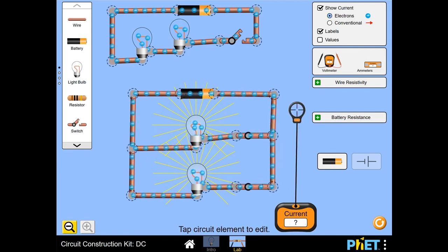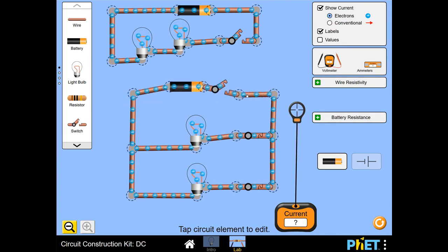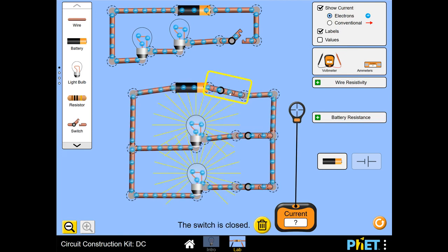Now, it would also be possible, just because of the way the circuit works, if I was to disconnect this one here a second, and if I was to put a switch in up here, this switch, because it's in the part of the circuit which controls both of the lamps, will turn on both the lamps together and off, both of them. Because in this top part of the circuit, the whole of the current has to go through here.